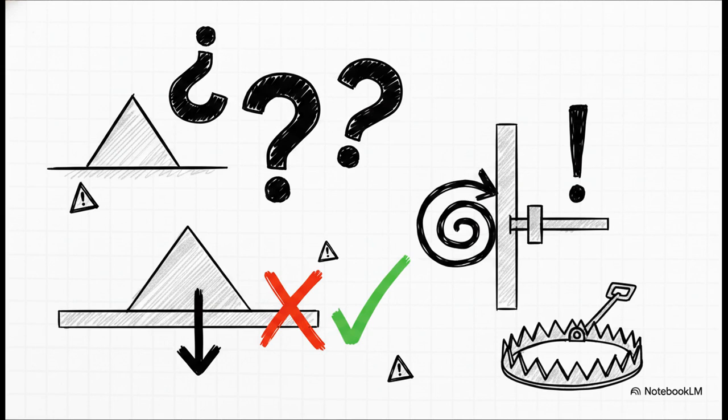Finally, let's talk about lost points. Consider this a warning label for your next exam. The most common pitfalls students make under pressure are forgetting that hinged supports require resolving into both horizontal and vertical components, totally misplacing the center of gravity when converting those tricky triangle UVL loads, and finally, completely missing the restraint moments when drawing fixed supports. Keep this checklist in mind and double-check your diagrams before you even touch a calculator.